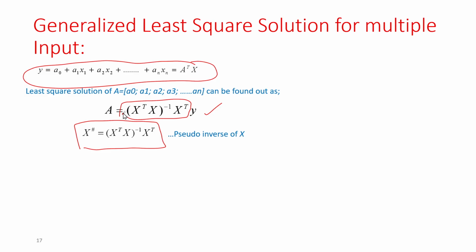Again, I am repeating only one thing: least square solution is good when you have some prior knowledge of the system dynamics. If the measurement is too nonlinear and you have no knowledge of the system dynamics, least square will be difficult, at least linear least square. Then there are nonlinear least square, Levenberg-Marquardt, and other algorithms like spline fittings, piecewise linear, orthogonal linearization. These are advanced methods that can be discussed later.